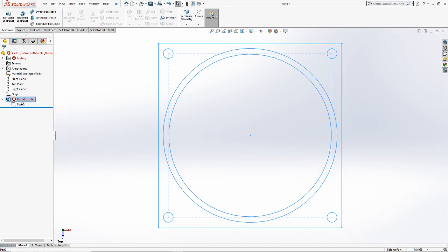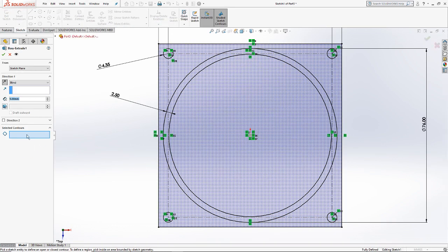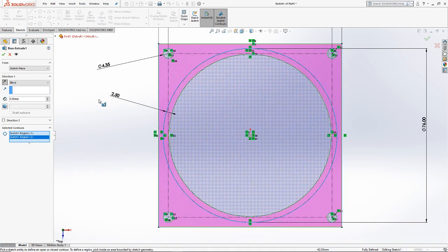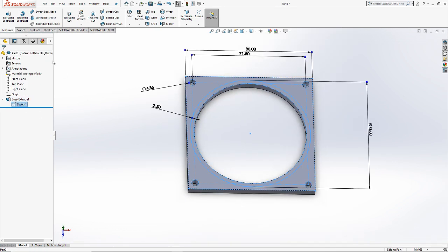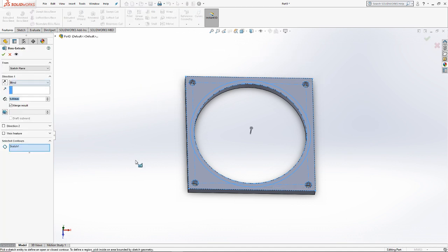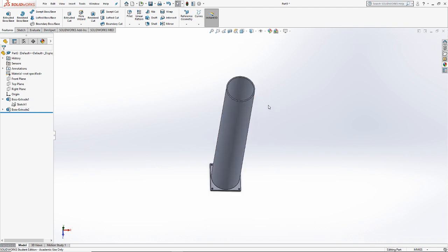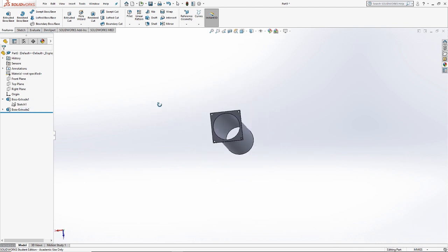So what happened is I modified my sketch. It doesn't know what my contour is because I didn't initially define it. Now I'm telling it what it was just to keep it happy. So if I go back in and extrude off of my sketch and say, hey, this time I want to extrude specifically this inside annulus, maybe 500 millimeters. That should be nice. Now I've got a duct.